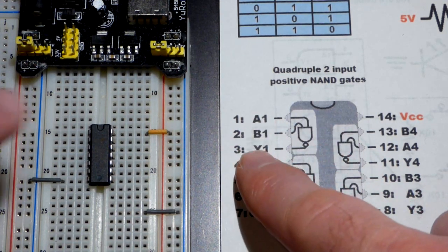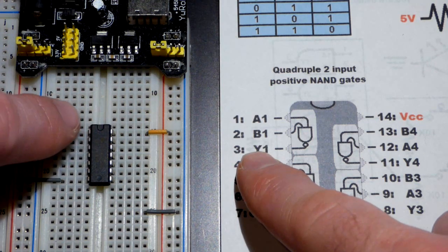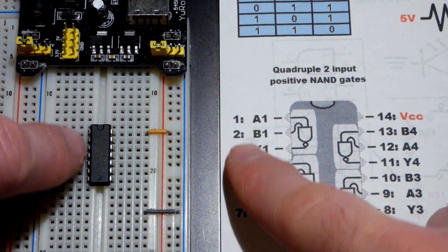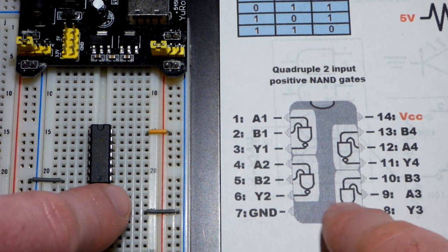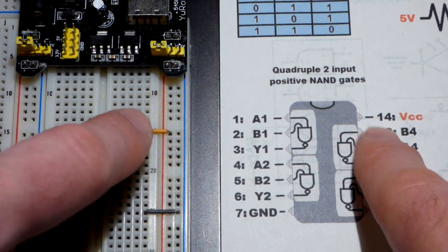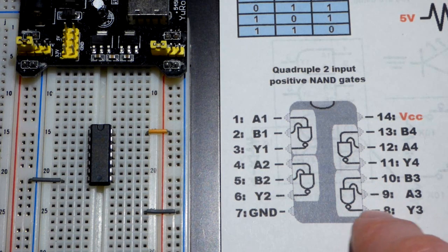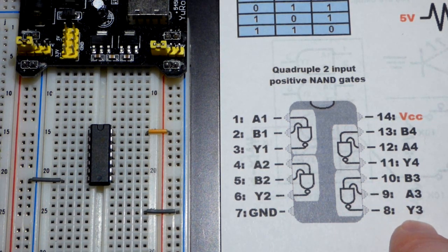As you can see there, it's a dual inline package. So you can see the divot there. Off to the left there is pin number 1, and you work your way down. So there's 14 total pins. We get to 7 down here, the ground, which I already have there. Then we jump over and we work our way up, so 8 to 14. And so I like that the output is right down there at the bottom for that one.